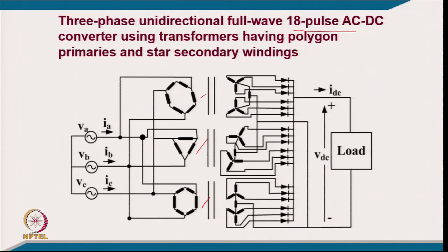So you are getting a phase shift of 20 degrees from one phase to the next consecutively, and you are able to use the 18 phase supply for an 18 pulse converter with 18 diodes, and here you will get 18 pulse in the output. Of course, in the input you will also get harmonic orders of 18 plus minus 1, so the 17th will be the lowest harmonic. That will improve the power quality on the input as well as increase the number of pulses in the output.